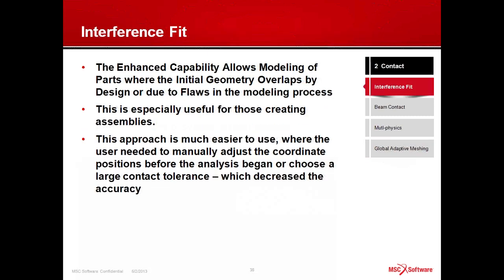So contact, of course, is an important technology. We always say you've got to have a little bit of contact in your life, and this is an area that we focused on, and we have produced a lot of interesting technology with this release. The first one I want to talk about is interference fit. Previously, the interference fit could only deal with small overlap of the particular bodies. It was limited to being within the size of the contact tolerance.